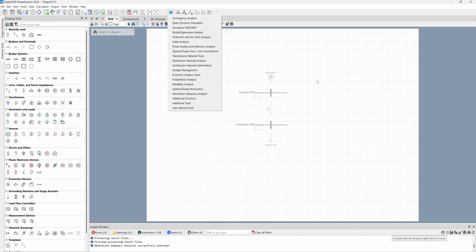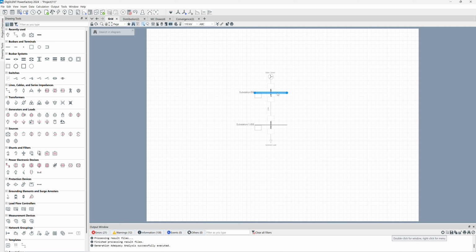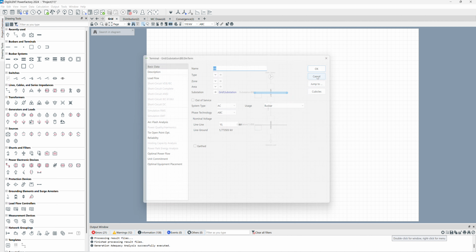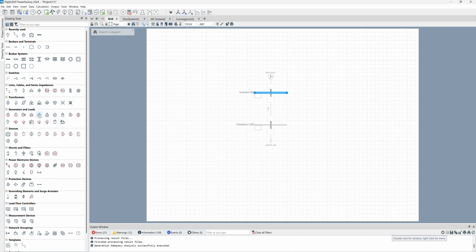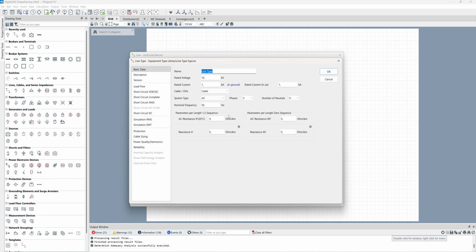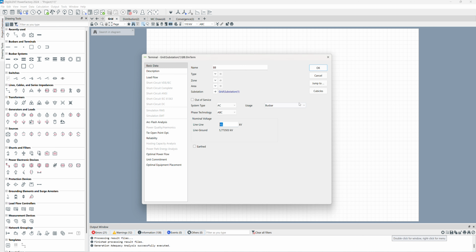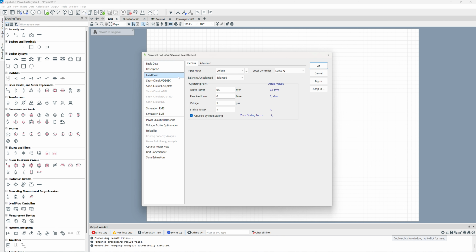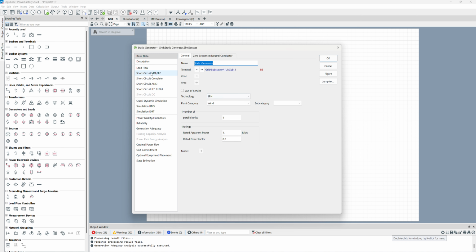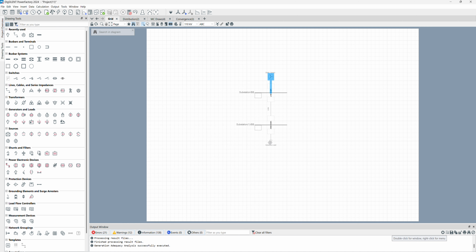So for this reason, we just installed one wind turbine to a 10 kilovolt busbar, and the wind turbine can be found from these drawing tools. Just another one line without any specific values, just 10 kilovolt to keep the load flow running. And the load that we connected is 0.5 megawatt, and the wind capacity is 1 MW, so it's twice this load.